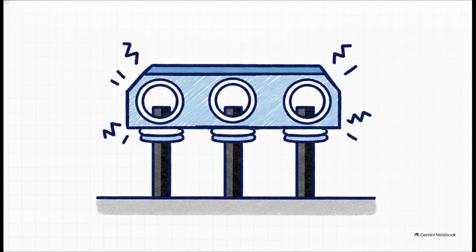But wait, this is where things get genuinely wild. What happens when we throw maximum material condition, or MMC, into the mix for our datum pattern? If we specify MMC, our simulator pins are fixed at the virtual condition, basically the smallest allowable holes. If the machinist drills those holes even a little bit larger than the smallest limit, they gain what we call bonus tolerance. The physical holes are now larger than the perfect simulator pins, meaning the part can legally shift or wiggle around on the fixture. So that best fit center of your part, it just became highly dynamic.